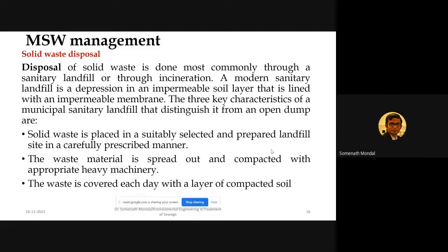Many a time you may encounter a question: what is the difference between incineration and pyrolysis? So the main answer lies in the fact that in case of pyrolysis, you don't need oxygen. The pyrolysis process is conducted in the absence of oxygen, and usually the temperature is also lower compared to incineration. In the case of pyrolysis, we have temperatures from 200 to 900 degrees centigrade, and the product of pyrolysis is basically gas having relatively higher calorific value, around 20,000 joules per gram, and then you can have some oil, tars, and solid char residue as well.